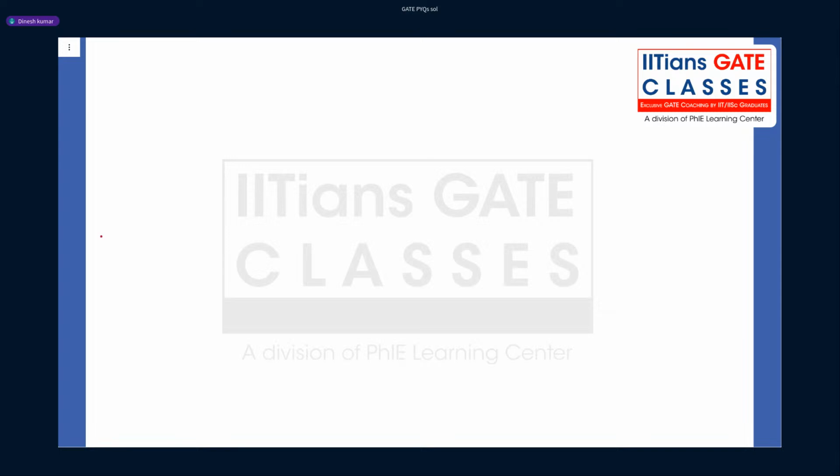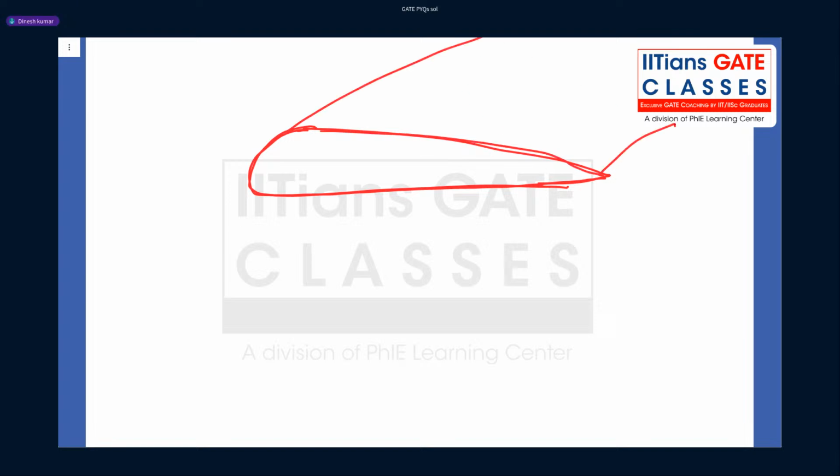So guys, if you see the semi-monocoque structure of a wing, you can see this is the shape of the wing, and this is how the spars are positioned. Suppose in this wing there are two spars, the front and back spar. This is known as the spar cap, which primarily carries what?